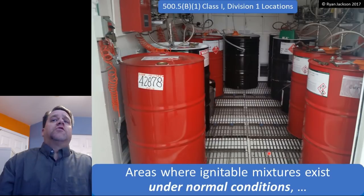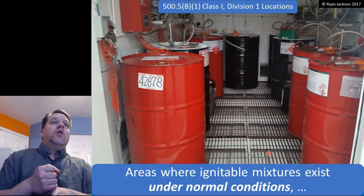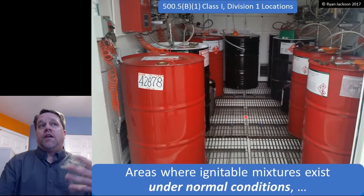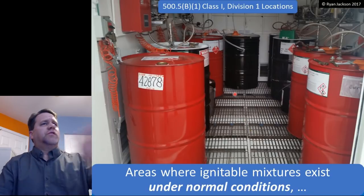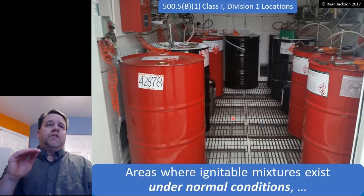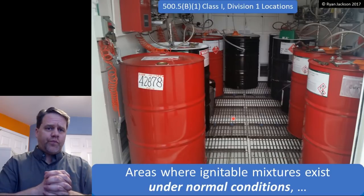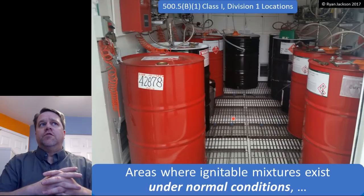So it's an area. It's going to depend on what? The vapor density. It's going to depend on the upper and lower flammable limits, right? What percentages of vapors are required to have an ignitable mixture. Maybe this is open to the outside and there's all sorts of ventilation going through, and it's maybe not as big of a concern. So I need to look at the vapor density, how heavy it is. I need to look at the upper and lower flammable limits to figure out how much ventilation exists or needs to happen. I'm going to be looking at all sorts of different properties of the individual chemical.